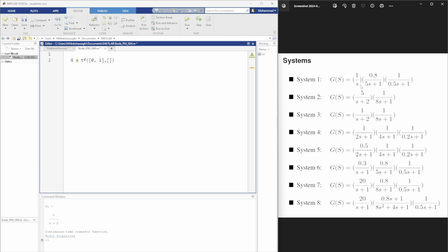In the denominator, by the way, we have s. Starting with the maximum power of s, we have a coefficient of 1. On the other hand, it doesn't have any constant value, so we would have 1, comma 0. That essentially would create this transfer function. We can easily see how it turns out with Control Enter, and at the bottom of the command window, you can see that G is represented as 1 over s, and we can verify that our assumption was correct. So again, the numerator and denominator are given with coefficients starting with the maximum power of s, moving down to the lower power of s, or constant value.